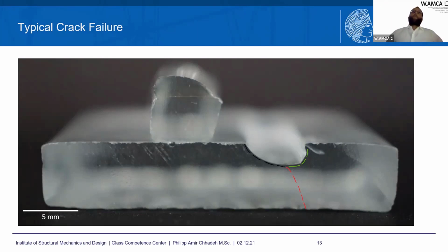This is beautiful. We see a 45-degree angle where the crack starts. That transformation of a pure shear notch into a pure tensile stress state. Then the crack travels in a mode 2 dominated shear field, where cracks tend to be 70 degrees out of plane. That's the red thing that you see. Yeah, this is perfect continuum. So thank you for being the middle of the show. But it's actually good to see that it checks out with the theoretical part.